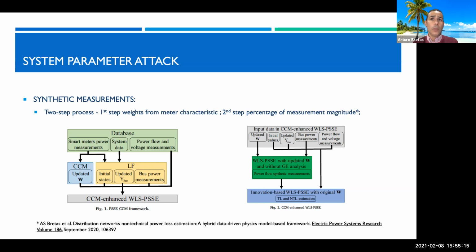We came to the challenge that this might not hold for all areas of the system, meaning that you might have an overall global redundancy level that is above 3, but in certain areas you might have a value that is not. So you might have areas in your system with fewer measurements and the redundancy is smaller. And of course, in a logical sense, those areas are more prone to failure for your detection and identification tests, because your assumption is further away from the truth. That's seen numerically through several tests, and even analytically through the analysis of the error itself.